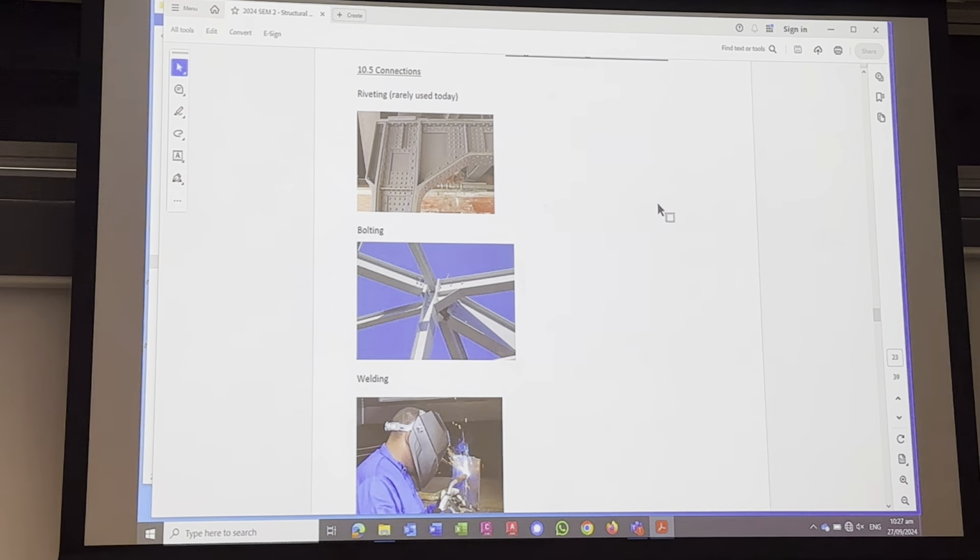Most of the older bridges are riveted, but they did find out in all sorts of ways that the rivets were the weak point on the bridge. Obviously, if they all pop, suddenly the structure falls apart. So they very quickly realised that the rivets had to be protected, in bridges particularly. The only way of protecting them was to paint them, and paint them every year.